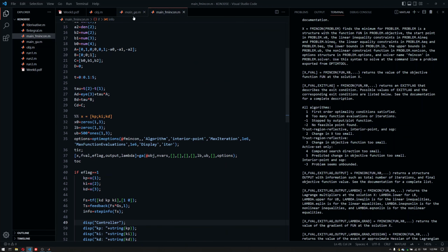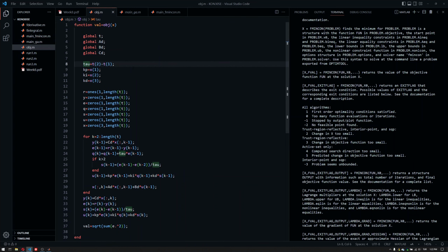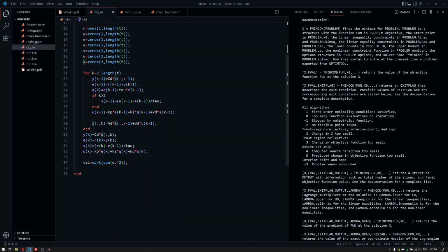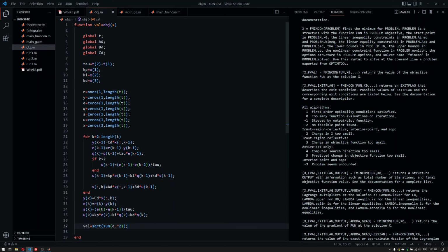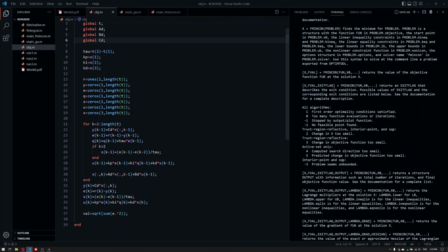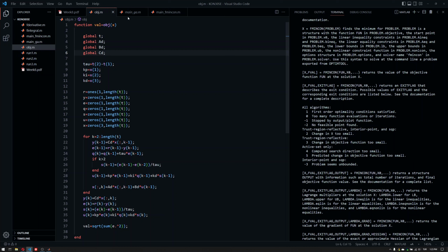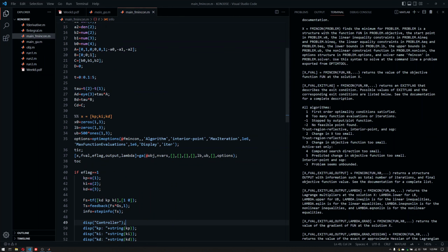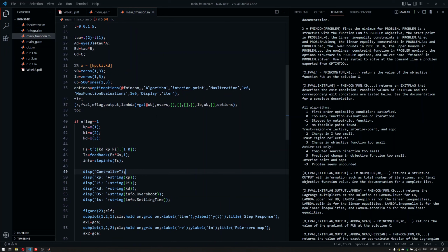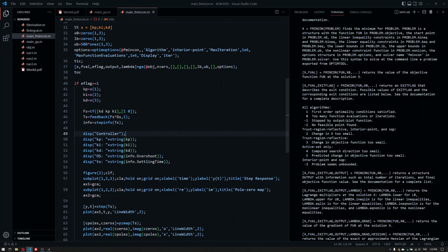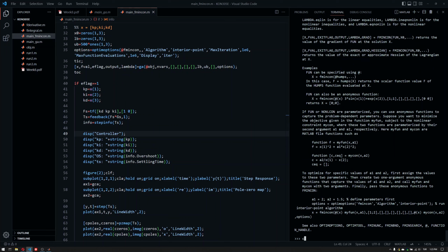So I didn't basically change the objective function here because the objective function is between x, some decision variables, and the value. Everything between these two definitions is basically covered with this global stuff here that is necessary to calculate stuff, and it doesn't really depend on anything else. So if we have those, we're good to go. So we can use the same objective function if we code it more universal with the main GA with a genetic algorithm, or we can change the solver here, and we can then run that one here.